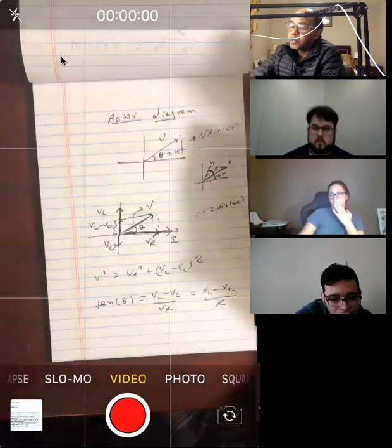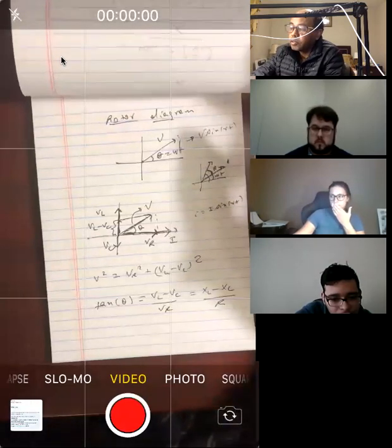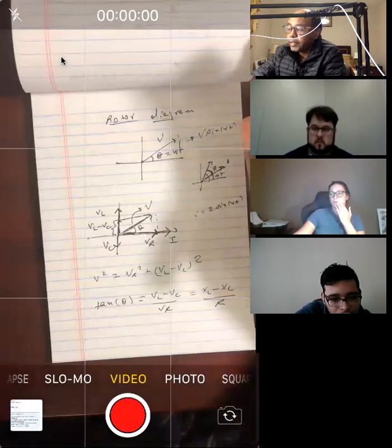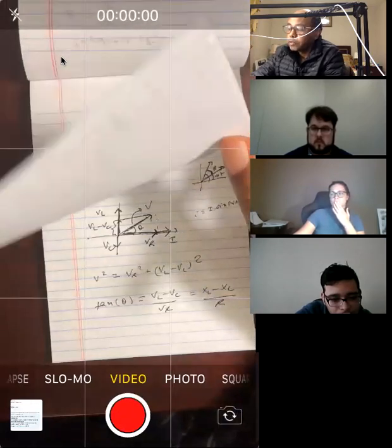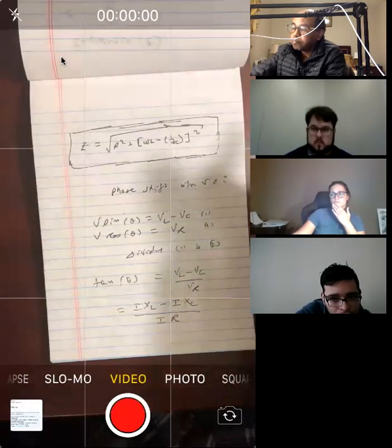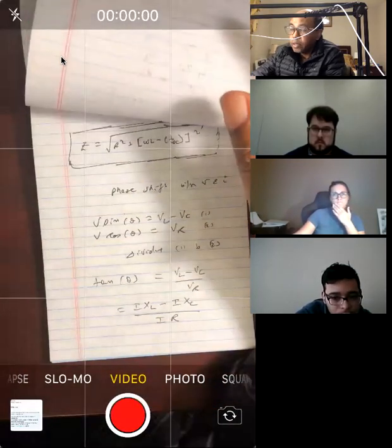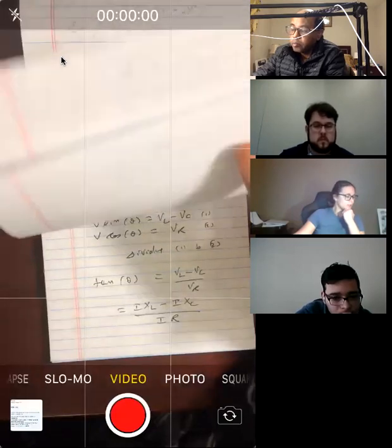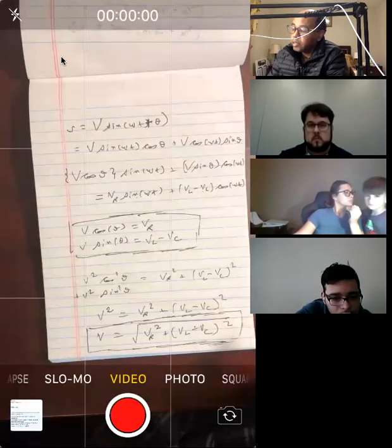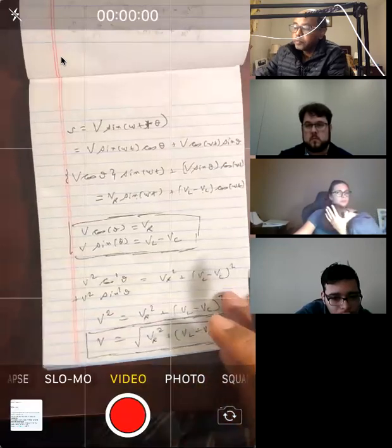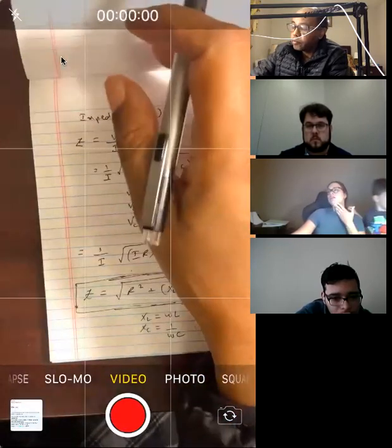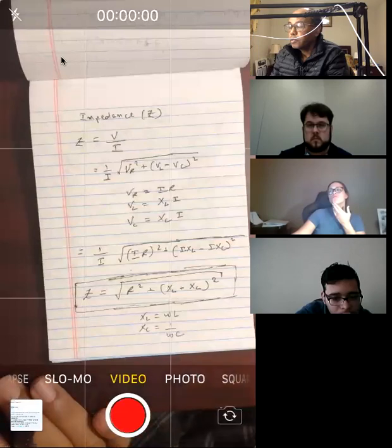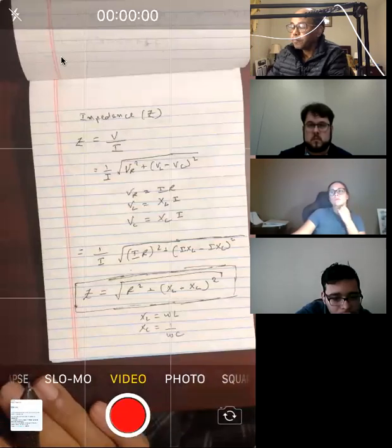So that's how we deal with series combination of a resistor, inductor, and capacitor, okay? The voltages are added like vectors. The instantaneous values are added algebraically, like in a DC circuit, but the amplitudes are added like vectors, okay? And then of course, we have the impedance over here, the impedance of the total circuit, all right?